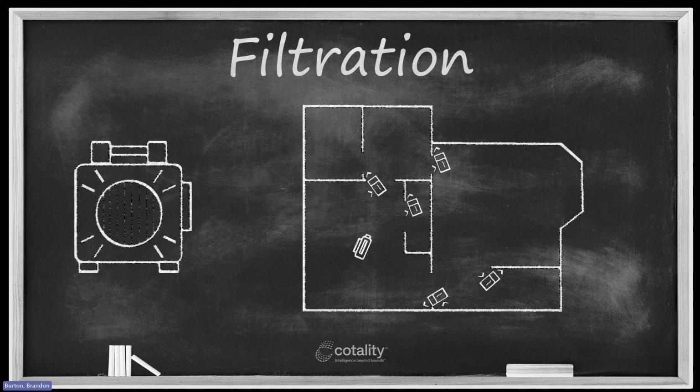All right, so I've got air movers that have an intake from one room, exhaust into the next. I'm getting good air exchange between all of my rooms already. So now there's no reason to be fancy with my air scrubber. There's no reason to have its intake in one room and exhaust in the next or use ductwork. I don't need to do any of that.